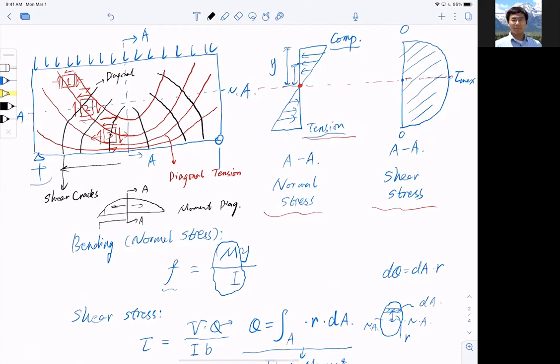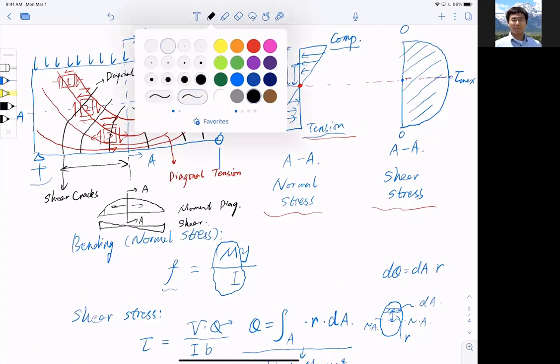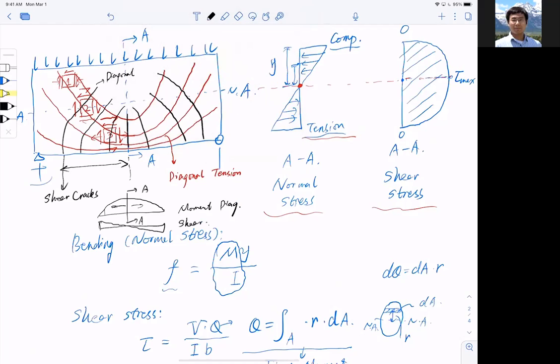And the shear diagram looks like a triangle, actually, sorry. Looks like this. Shear. Right? And as I'm getting closer to the middle section, I see my cracks are more vertical. So these are the flexure cracks. And apologize for this very crowded drawing, but I just want you to see the whole picture. Okay. These are the flexure cracks.